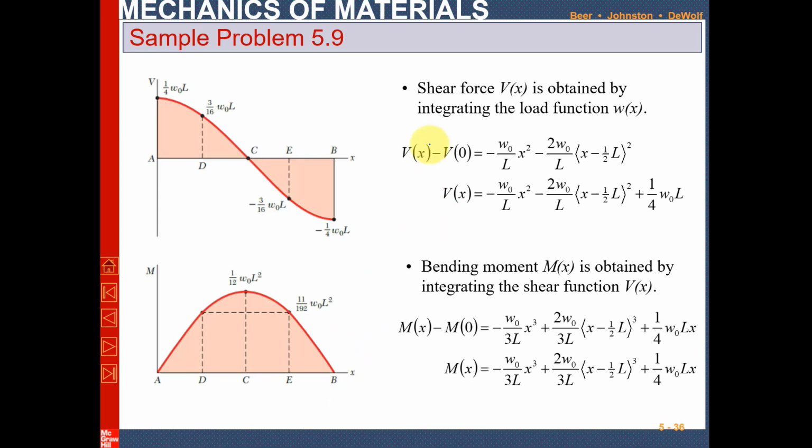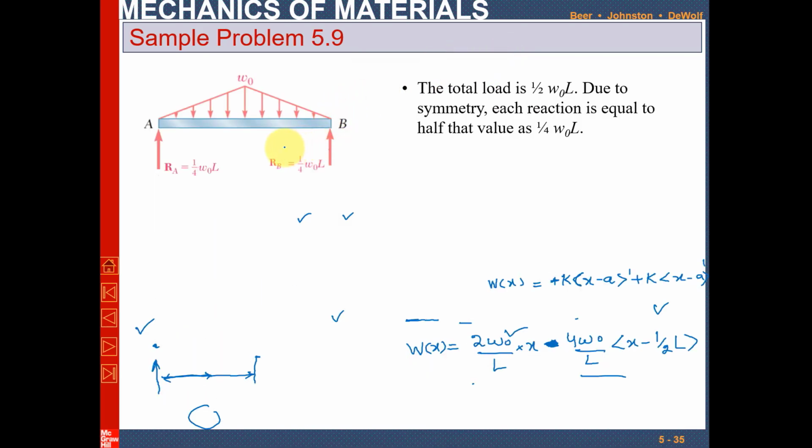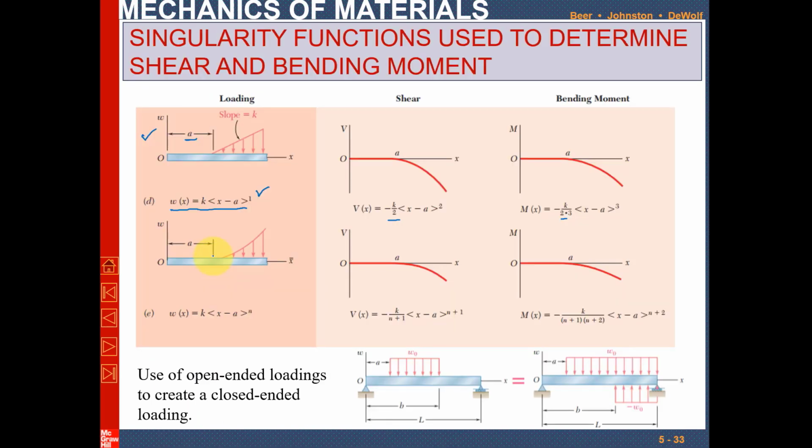Again, the shear force equation will be, I have written again, that is Vx is equal to minus k over 2 into x minus a to the power 2. Let me check it. The shear force is minus k by 2 into x minus a to the power 2.